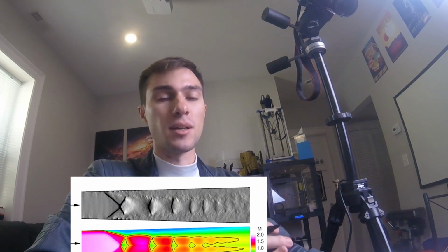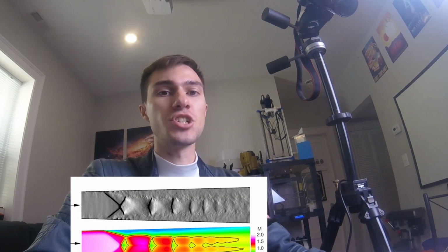Now, supersonic flow complicates this because supersonic fluids can have shock waves, and shock waves break the isentropic assumption, because in shock waves you lose energy to irreversible processes. So shock waves do really weird things to your flow and ruin your isentropic flow assumptions. Shock waves typically form near corners in nozzles, also at sharp points. If you think about an aircraft or a rocket flying supersonically, you get shock waves at the leading point of the vehicle and the trailing edge, and also at the roots of the wings and the tips of the wings and things like that. So shock waves, not good, but we kind of have to deal with them as a fact of life of working with supersonic flow.